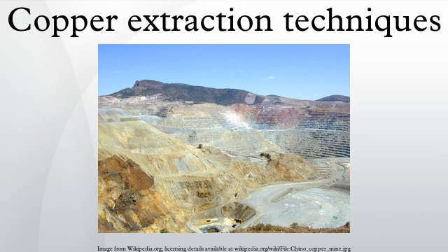The copper sulfate solution is then stripped of copper via a solvent extraction and electrowinning plant, with the barren sulfuric acid recycled back onto the heaps. Alternatively, the copper can be precipitated out of the pregnant solution by contacting it with scrap iron, a process called cementation. Cement copper is normally less pure than SXEW copper. Commonly sulfuric acid is used as a leachant for copper oxide, although it is possible to use water, particularly for ores rich in ultra-soluble sulfate minerals.